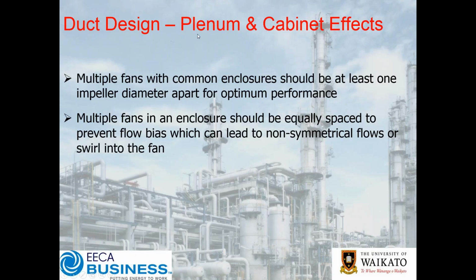Now the other thing, of course, is when you have multiple fans with common enclosures, they should be separated, as we're saying, and then obviously you want to have equal spacing so that you've got air going to all the fans. Now often many of you will have systems where your fans aren't all the same size, and so this is where you want to make sure that you've got plenty of plenum space in that fan room, so that you don't have any one fan hogging all of the air, so that you've got good even distribution.